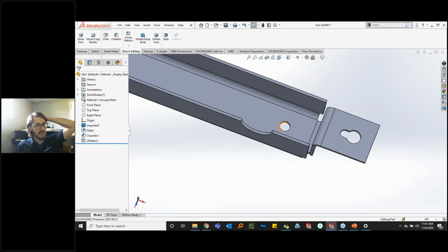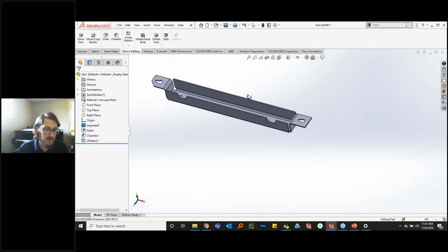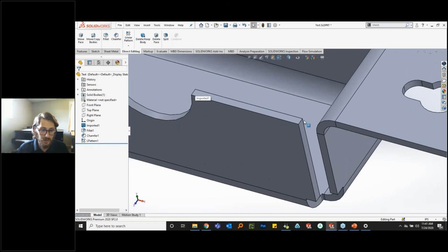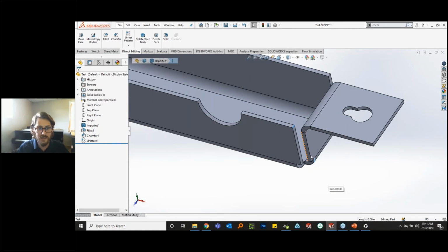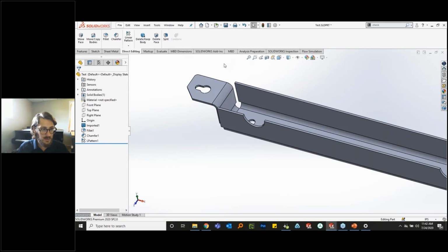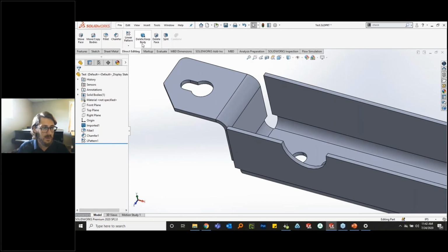Let's say for instance that this sheet metal component that came through is not the right thickness. I'll click on an edge here and measure, showing down here that it's 0.60, so that's too light of a wall. We need something that's a little heavier gauge, and we need that corrected effectively. So let's go ahead and play with that. What we can do here is we can just basically extrude the faces. We can offset the faces a little bit and move them to give us an increased thickness.